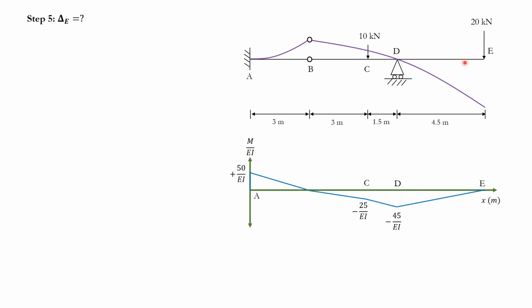So the deflection I'm looking for is this one, of course, delta E, right? But what I'm going to do, I'm going to draw a deflection, the slope, the deviation from point D. I'm going to measure it at E. So this delta E I'm looking for. But I'm going to draw this slope here from point D and measure it at point E from the curve. So this value will be tE with respect to D, right? And this value will be psi. Now, what is this psi? Well, this is a triangle.